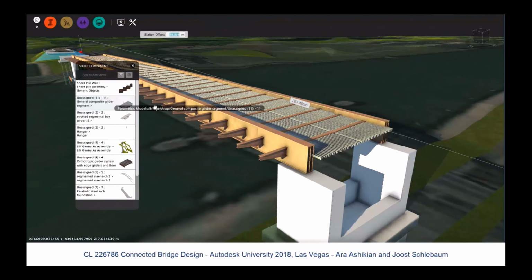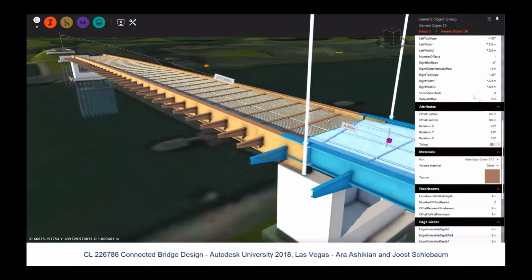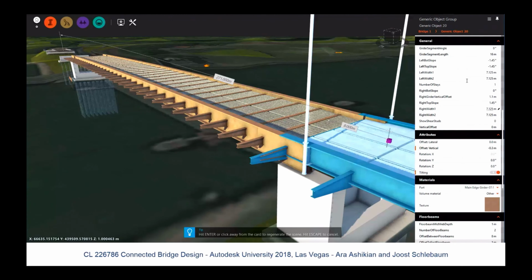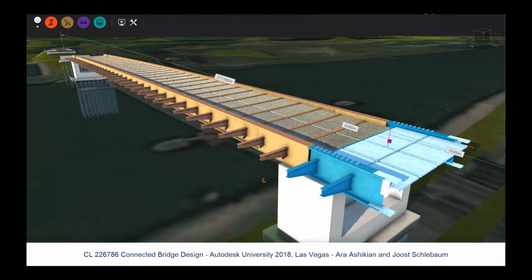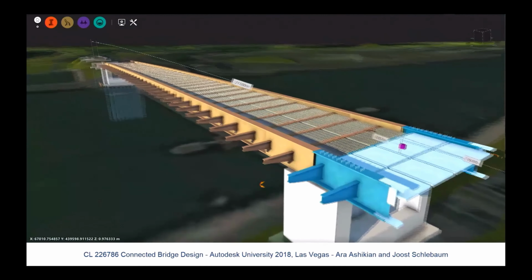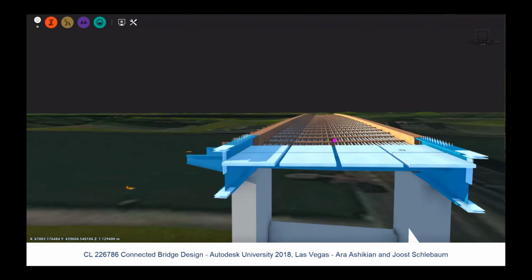And then I'm going to pick a slightly different composite box girder. You'll notice at the beginning, it was meant to include details for hangers and Inventor and so on. I'm going to turn those off and make it just a precast composite for the approach span. So I'm just playing with the parameters in here. Remove the hangers and reduce the number of floor beams. And you can see you can turn on details, whether you have field splices or shear studs. It doesn't matter, right? Add whatever you think you need. If you're going to reuse this over and over again, might as well add as much. Or maybe you start simple and in the next project you refine the part.